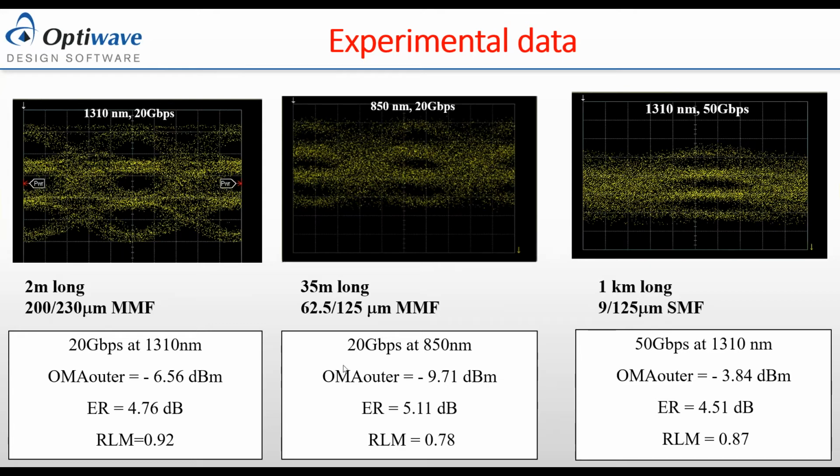Now the last slide, on the right side, we use again the same 1310 nanometer, but instead of using 10 gigabit per channel, we used commercially available QSFPs, made in China. We combine them together using not state-of-the-art equipment, but a simple checker from Gigalite that will drive all four lasers in the least expensive fashion, probably $1,000 equipment each.